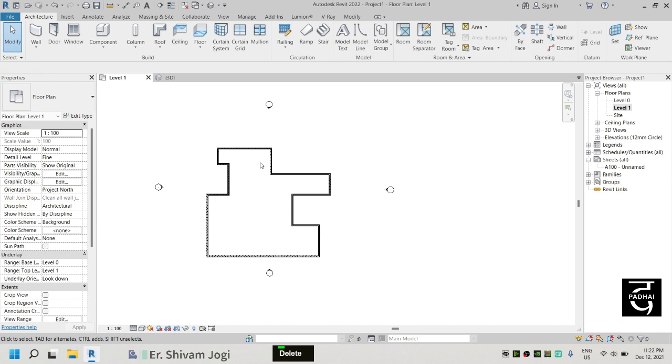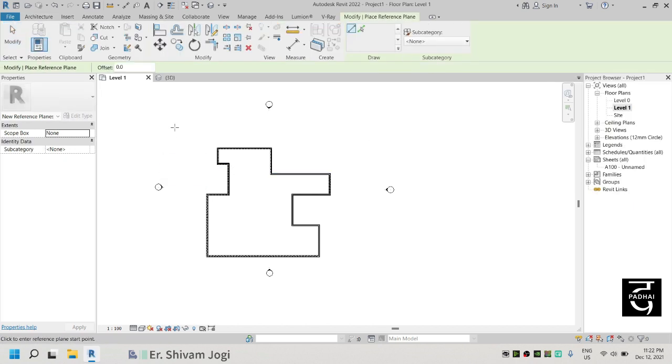Now before we begin drawing the roof by extrusion, you need to provide different reference planes. On the right hand side of the screen in the architecture tab, you can see that you have an option called work plane. We will learn about this option in depth. For now, all you need to know is that you can draw reference planes from this, to which any of your drawing will be referred. In this case, I need to draw a reference plane for the starting point of the roof and the ending point of the roof. So I'll draw a line over here.